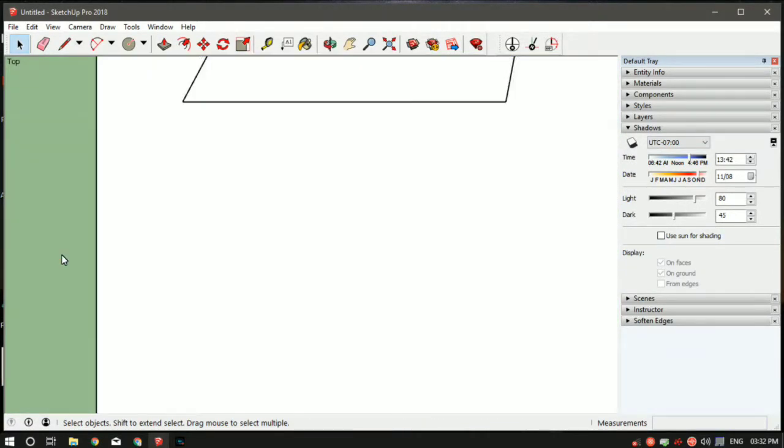What I'll do is I'll make lines with different dimensions, so you'll come to know the difference. Let me select the line command, shortcut is L, then just select the starting point and let me make a line which is 10 feet in height. For 10 feet, you've got to use the single apostrophe, then press enter. So this is now a line of 10 feet height. Press escape to come out. Again, select the starting point. I'll try to select the same starting point.